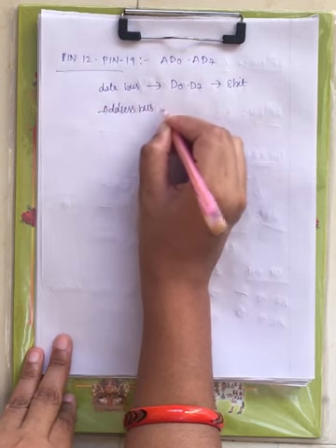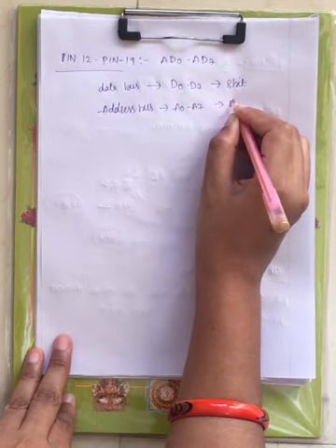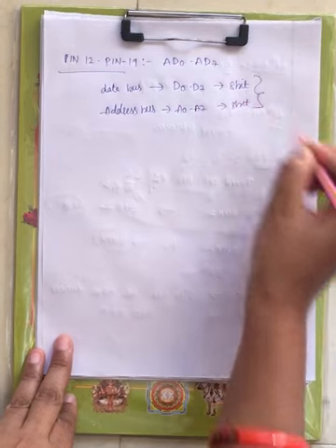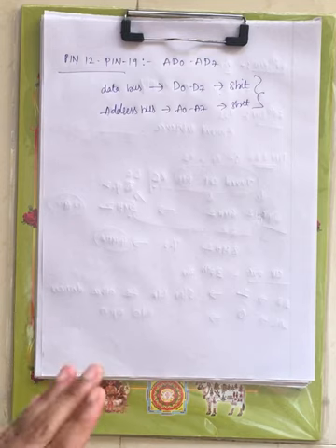Now here you have the address bus, that is A0 to A7, which is also 8 bit, right? Now these two are multiplexed, from pin number 12 to pin number 19. Now these two are multiplexed: lower order address and data bus.